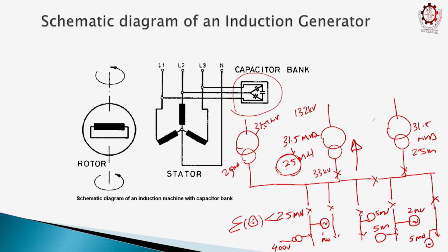Then grid connectivity again becomes possible. So, for that you have an augmentation expenditure for the addition of a new transformer, right. But keeping the n minus 1 criteria, you will have to check whether the plant is grid connectable before doing other investments, etc. Otherwise you will probably have to reduce your size. You proposed a 5 megawatt plant, they will say we can allow only 2.5 megawatt, the extra capacity available is 2.5 megawatt. So, reduce your size. Remember this part, therefore, you have to check the grid connectivity of the power plant.